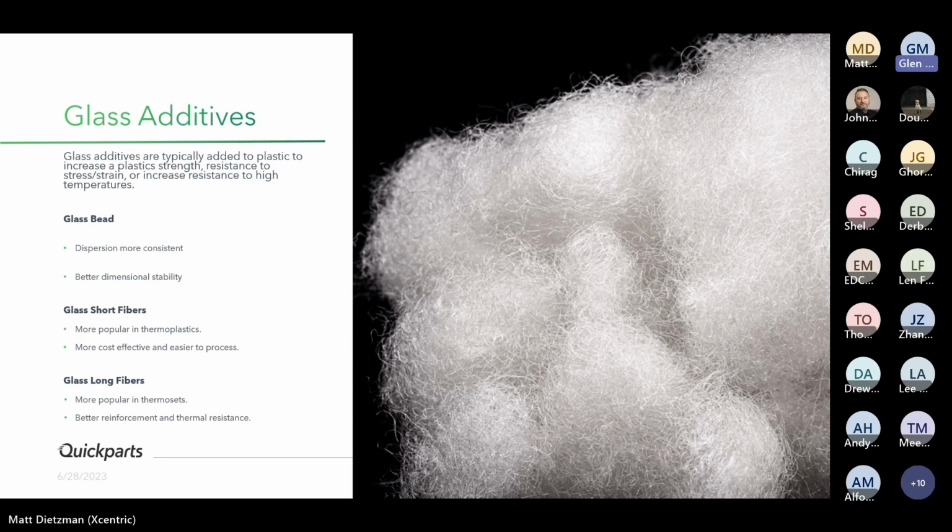We got three basic, I guess you call them classes. Glass bead. Dispersion is more consistent. The glass beads are consistent in their size and shape. They do provide a little better dimensional stability. The next type would be a short fiber. One of the more popular that we would use, a little more general, cost effective. It's very easy to process.